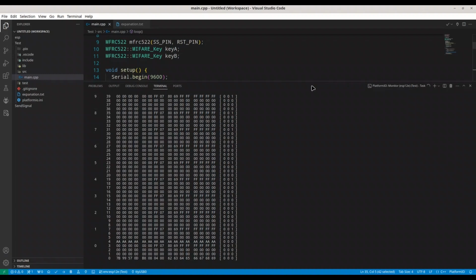Up to now I explained what the zero block is, which contains basic information about your card. Then I explained what trailer blocks are, and that every sector holds one trailer block or tail block. I heard that expression too. And I also explained that every sector holds data blocks. These card data blocks are mostly empty, so you are going to see mostly zeros, except this block number 4 that we used in our previous episode, and we filled it with bytes AA.